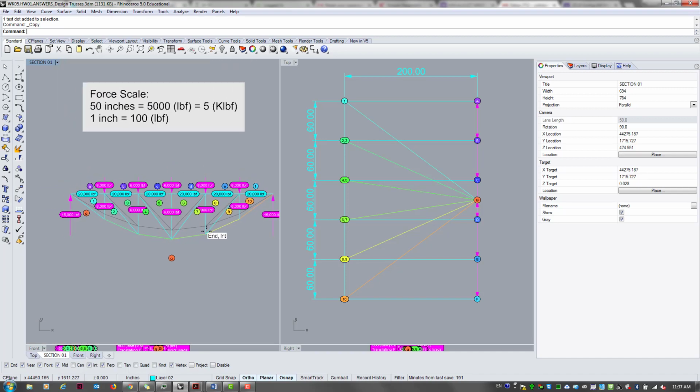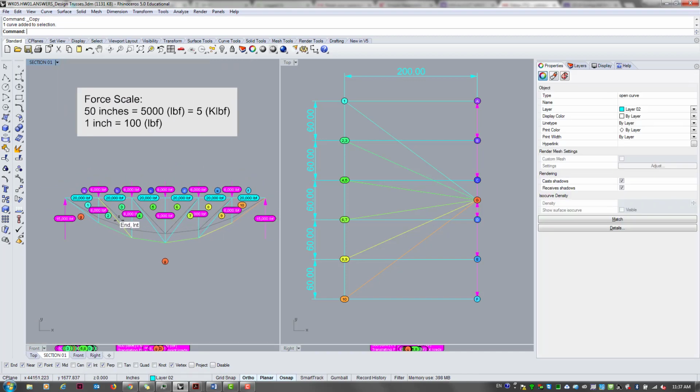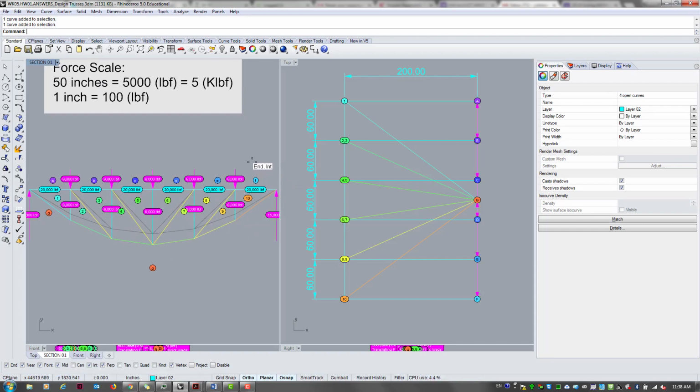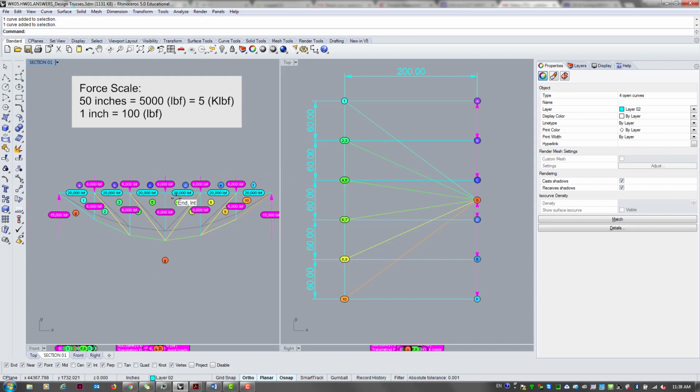And another thing is that all of these diagonal members, 2, 3, 4, 5, 6, 7, 8, 9, if you try to determine the dimension, for example, of line 2, 3, point 2 and point 3 is identical, so if you drew a line, it's going to be a length 0. So that diagonal member between 2 and 3 has a 0 force.